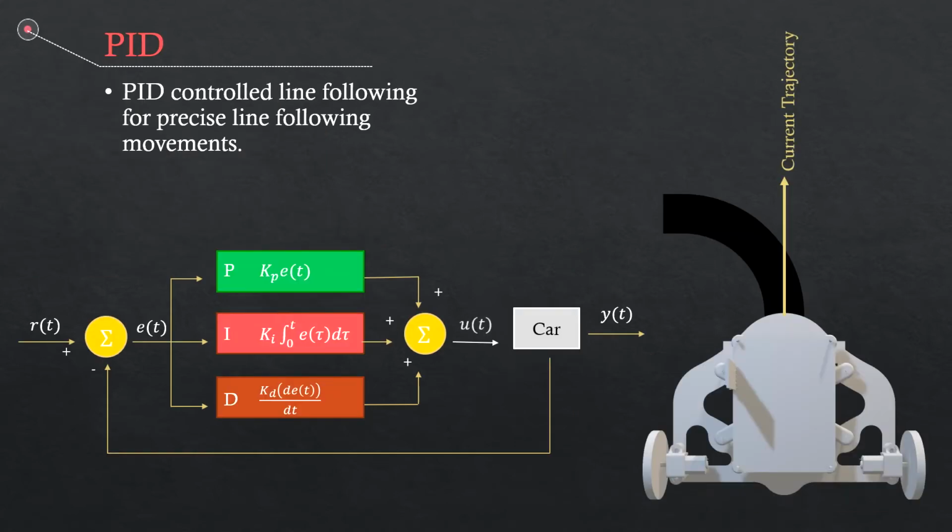One of the major updates on the robot was the implementation of a PID controller to dynamically adjust its trajectory to follow the line. Error for the PID controller was calculated as a weighted average of the car's position relative to the center of the line.